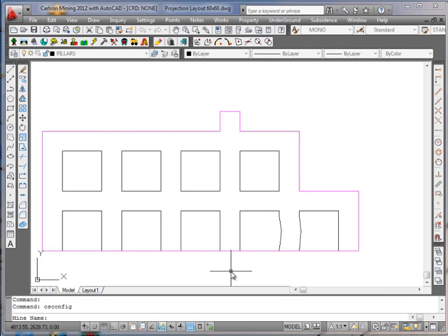We're going to build a series of prompts that allow us to enter the coal sections or the thickness measurements of the rock and the coal as the surveyors would identify them in the mines. And since we're going to build a report at the end of this that indicates how many tons were mined in a specific period in this mine, some of the prompts we're going to enter at this point will help build that report, such as the mine name. And I'll call this training-1.